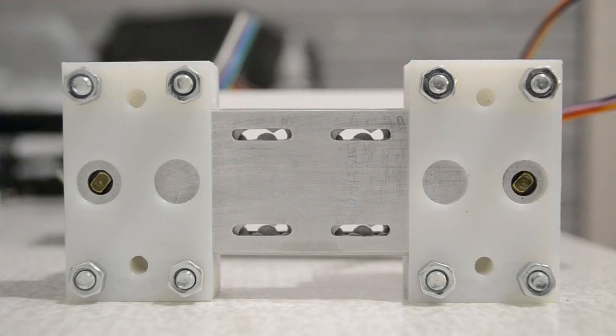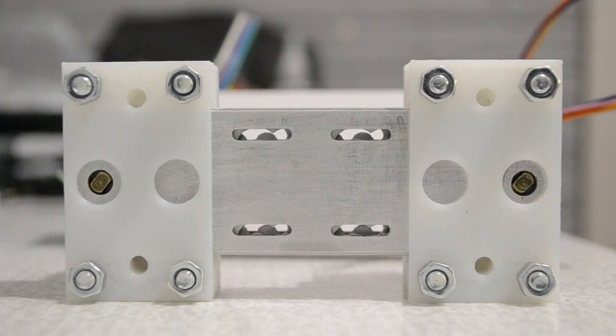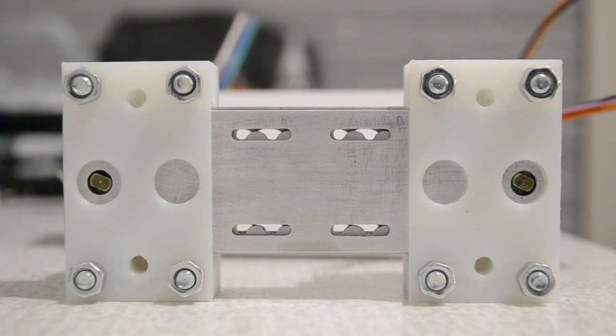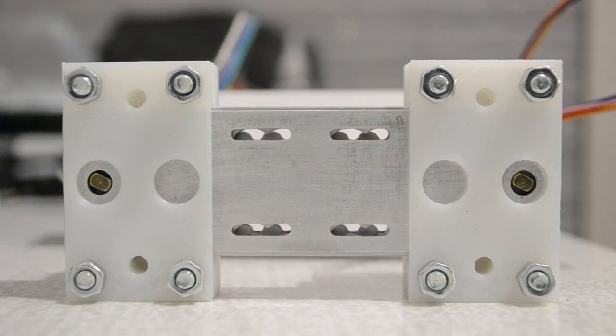Linear cycloidal drive has the following advantages. It has no screw drive, it has a slim planar design, and it has a great step distance in theory. Also, it has disadvantages. First of all, it's a really large backlash, and it has a high resistance, resulting in low pushing force because the pins are engaged with the edges of the cutouts.